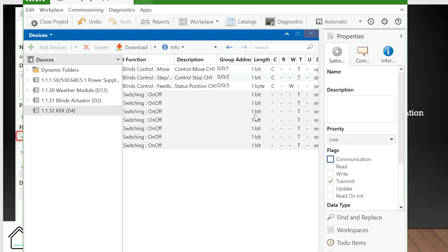So in KNX, the sender does not send the telegram again and again, 3 times, because it's already acknowledged. It means although the C flag is off and this group object is not working anymore, the acknowledgement is going on the bus. So by default, we never touch the C flag, but if you want to kill a group object, you should switch it off.